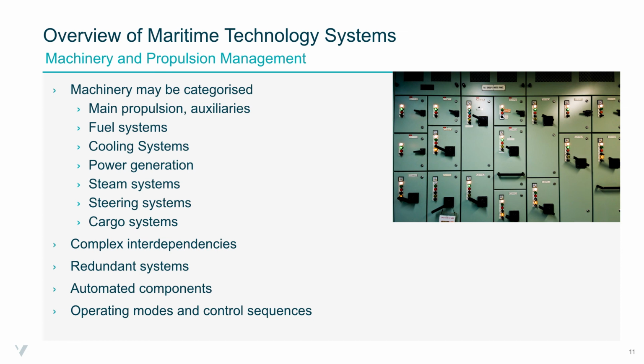Cargo systems, depending on the vessel type, integration to manage stability, to manage bending moments as part of the loading operation. To do this, these systems have to be tailored to the vessel that they're installed on. It has to have awareness of the capacities of the pumps and the tanks, and how much ballast can be moved by the pumps in a given hour, and provide that overall equilibrium so that the vessel stays within its operating specification.